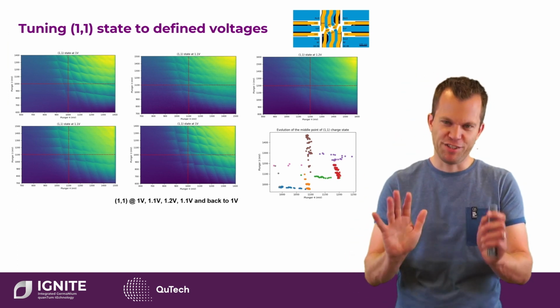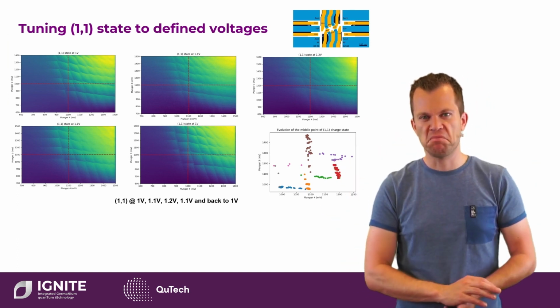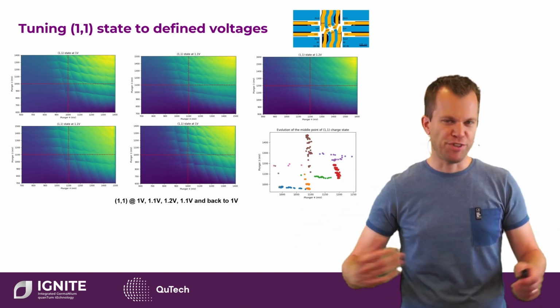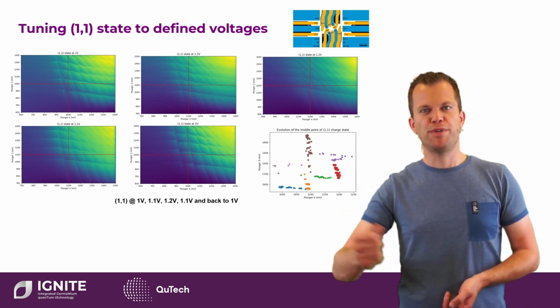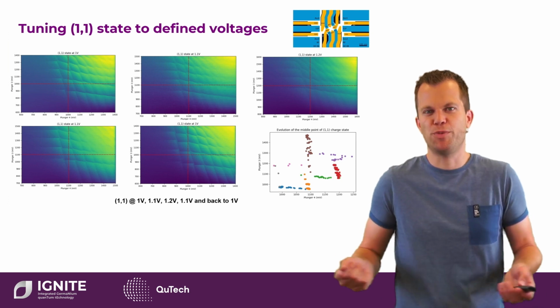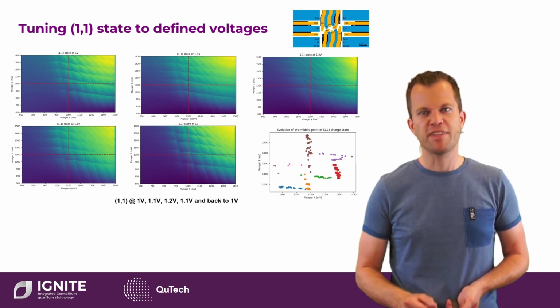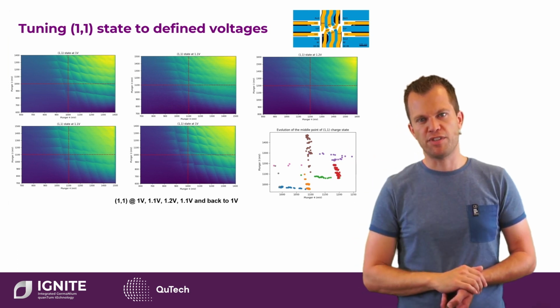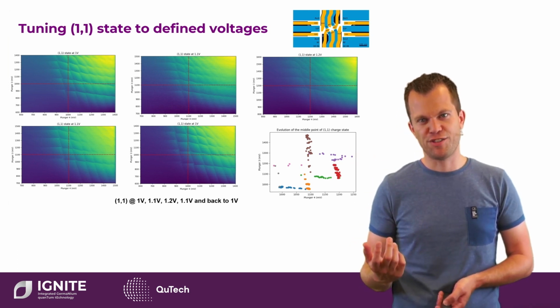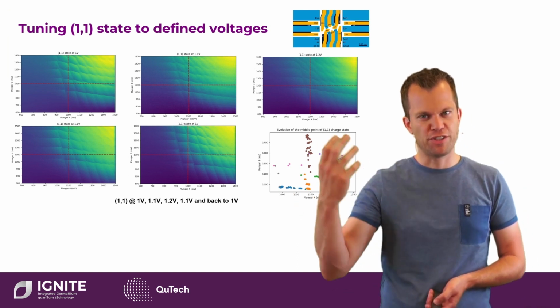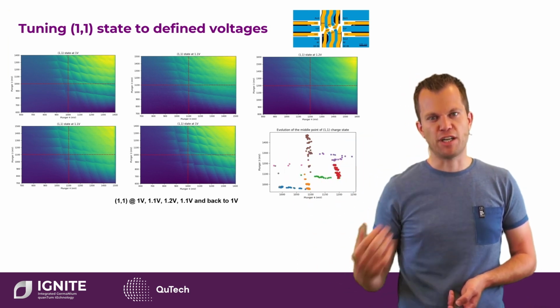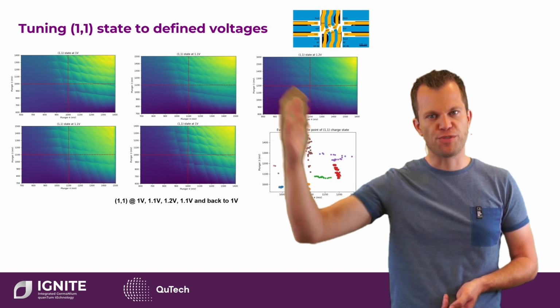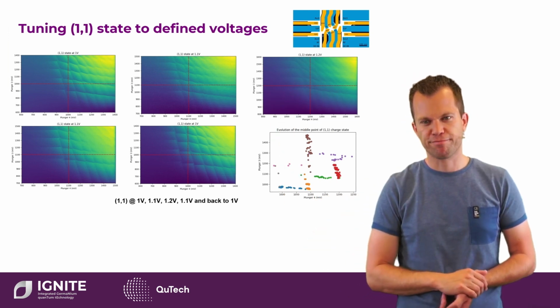Now one may argue, okay, this is great, you're making use of the traps. But if devices get better, if materials get better, maybe at some moment we don't have traps, because in the end we don't want to have noise, so these should go away. Then maybe there's a time where we'll see that heterostructures are going to be used, that we have additional layers to navigate and, for example, tune the lever arm in one quantum well by controlling another quantum well.